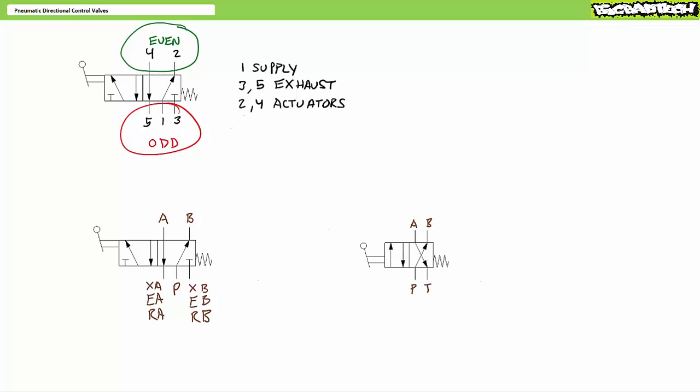You'll recall a lot of hydraulic directional control valves use this letter designation P, T, A, and B: pressure, tank, A and B actuator ports, so it's pretty understandable. The one variation being, rather than a single T return connection, as is common in hydraulics, most 5x2 directional control valves have independent exhausts for each actuator port. Which brings me to a point where I can explain why 4-port valves aren't as common as 5-port valves in pneumatic systems.